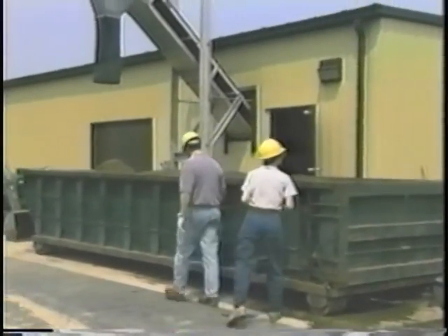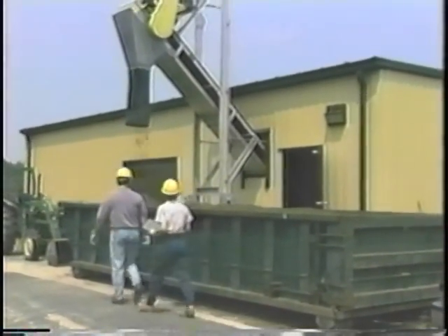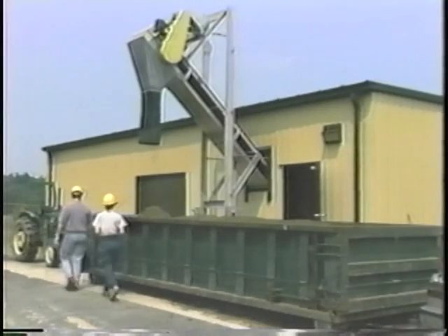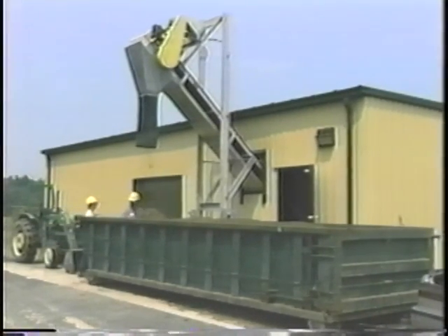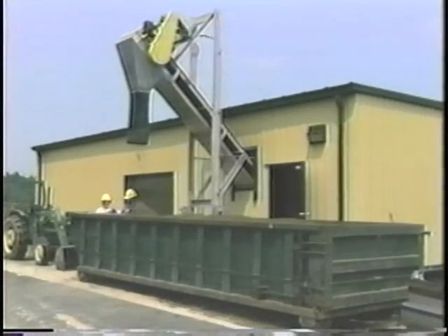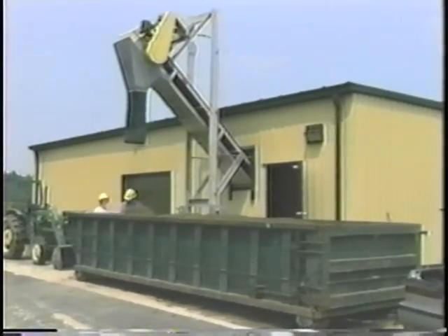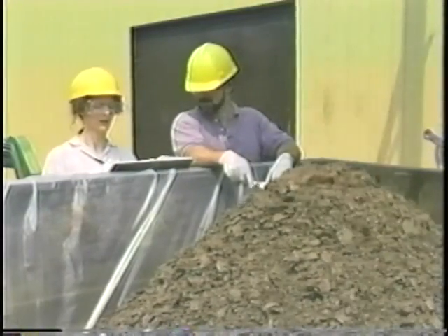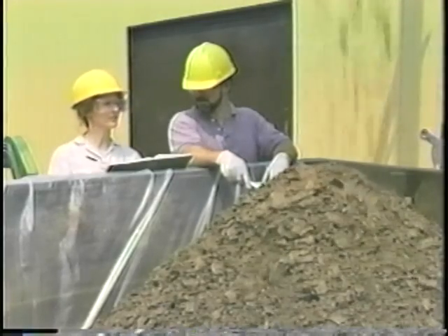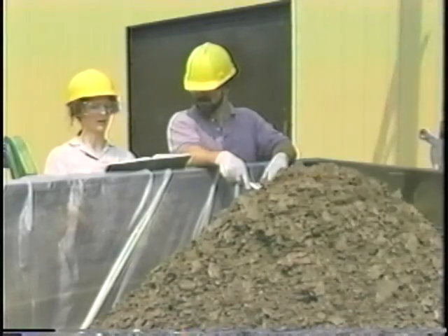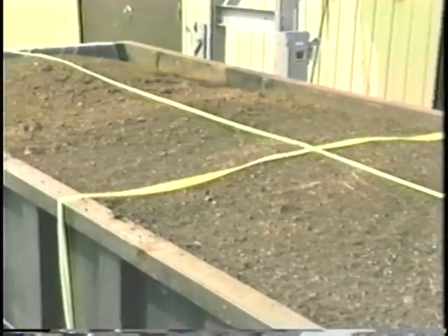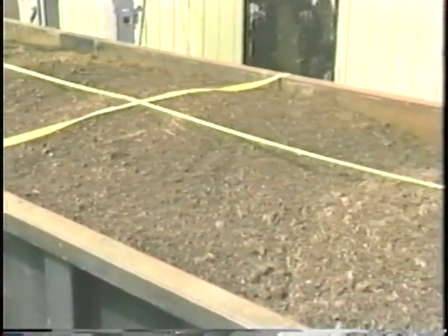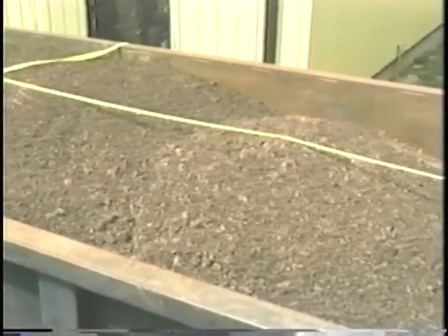Next, we will demonstrate how to collect a composite sample from a bin. The same sampling procedures can be used for a sludge drying bed, a truck bed, or other similar container. In your logbook, diagram the bin, dividing it into 4 quadrants, and mark the sample collection points. In order to collect a representative sample, equal sample volumes should be collected from the center of each of the